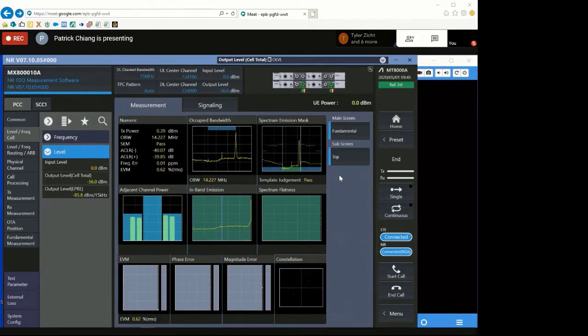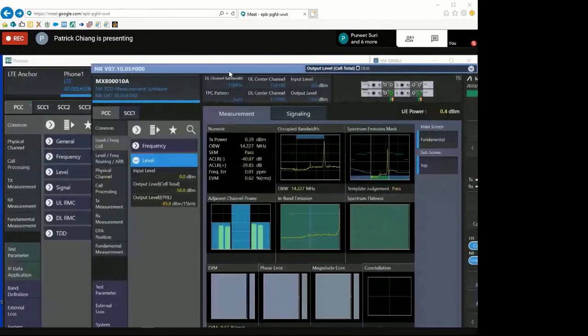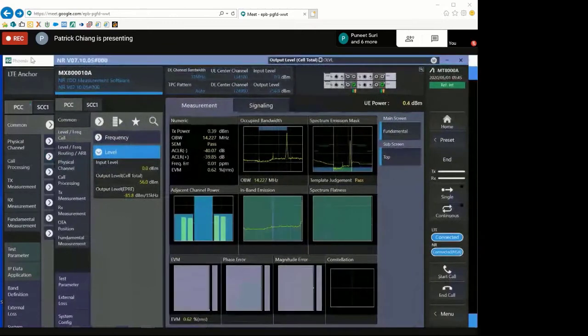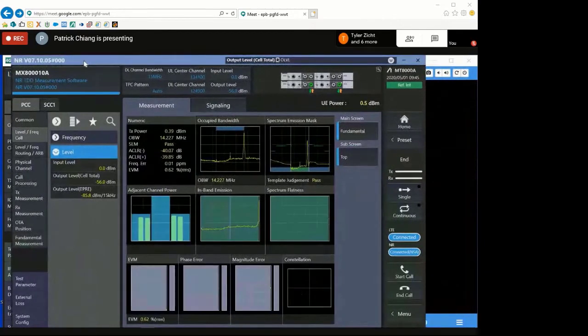So the ATS basically sends GPIB commands to this GUI to automate the test. Yeah, and it has the 3GPP judgment criteria built in, so it can tell you pass or fail. Got it. In our LTE solution we actually have that, but in NR, I think we will add it later in the GUI. But right now, the automation software will do the job. Okay.